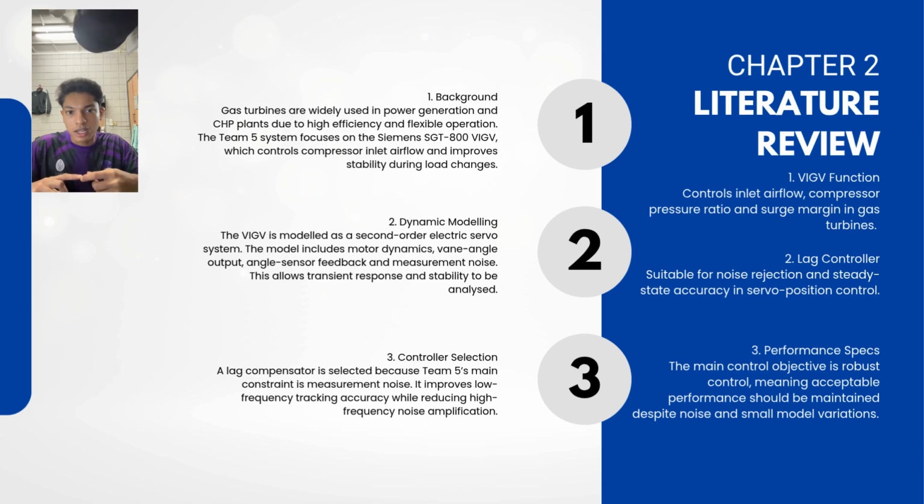Second is the dynamic modeling. The VIGV is modeled as a second order electro servo system. The model includes motor dynamics, vane angle output, angle sensor feedback, and also the measurement noise. This allows transient response and stability to be analyzed. And third is the selection of the controller. A lag compensator is selected because our team's main constraint is measurement noise. It improves low frequency tracking accuracy while reducing high frequency noise amplification.